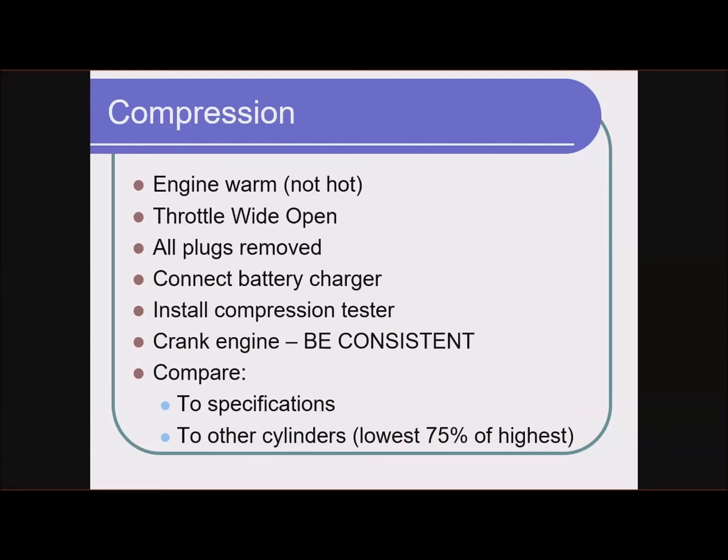So pull all the plugs, connect the battery charger. You're going to be operating the starter quite a bit during this test, so that is going to have a tendency to bring the battery level down. Install the compression tester and then crank the engine. One cylinder at a time, we're going to put the tester in, crank the engine. The important thing here is to be consistent. Do every cylinder the same way.